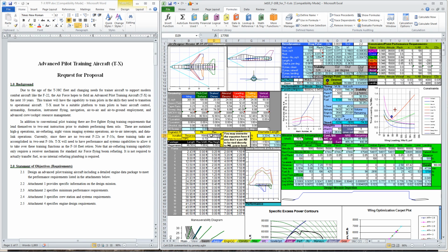We're going to make this equal to 17,700 divided by 11,000 times the actual value that we put in this cell here. Therefore, right now we're modeling the F404, but as we reduce the military thrust, we'll model smaller engines.